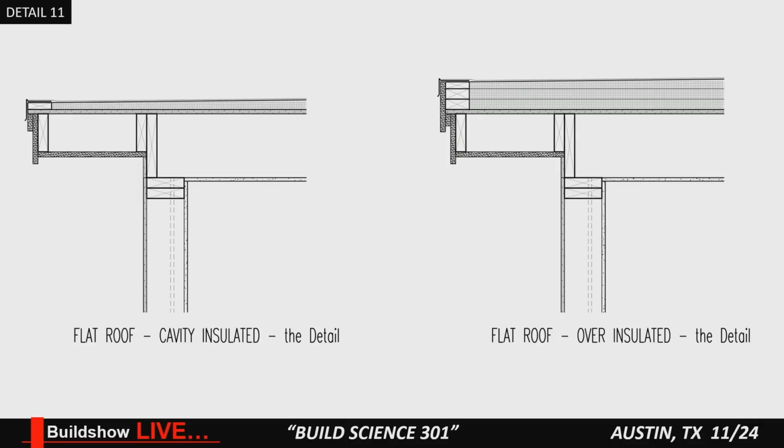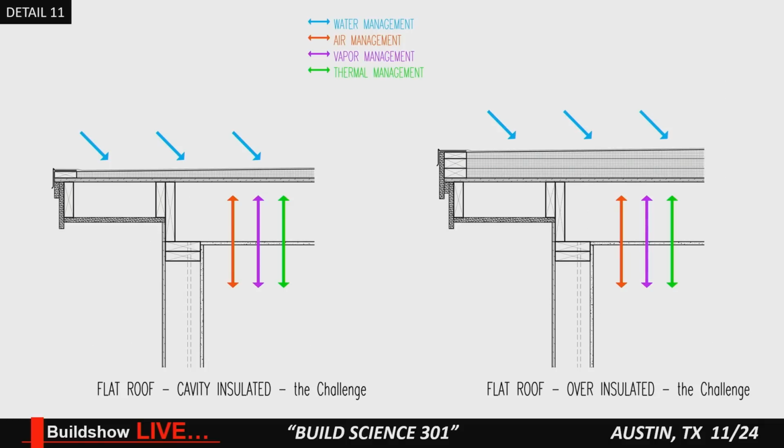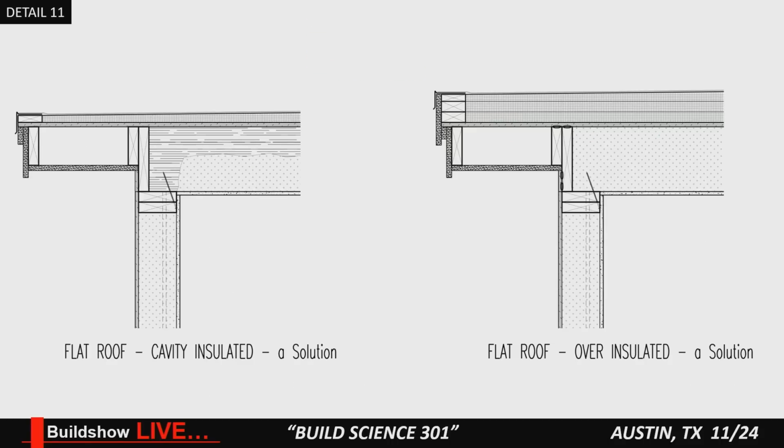I know. Flattish roofs, this is the end. Yeah, let's finish up with flat. Right. So flat roofs, you can either choose to insulate top side or put the insulation inside and handle the vapor profile on the inside of that sheathing, which on the left is what we're doing, right? We sprayed 4 inches of closed cell, impermeable, so moisture always stays in the vapor state, can't penetrate it, can't get to that cold sheathing on the roof.